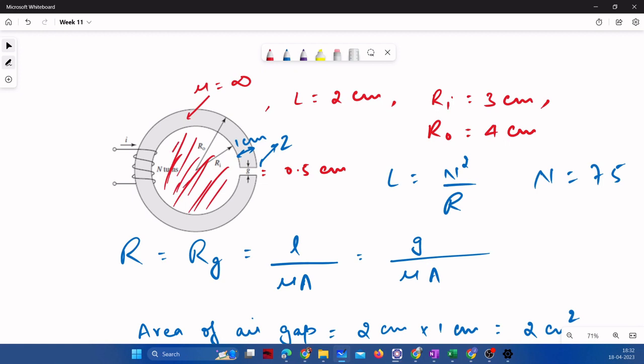This is the window area. So how much window you can utilize and where you can utilize more, that is another factor that helps in lighter weight design. Generally toroidal winding helps in lightweight design because it has relatively more window area.